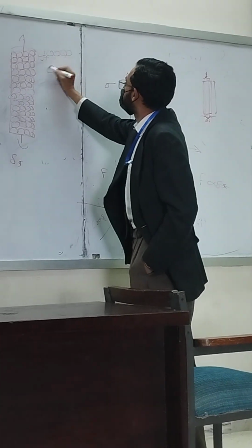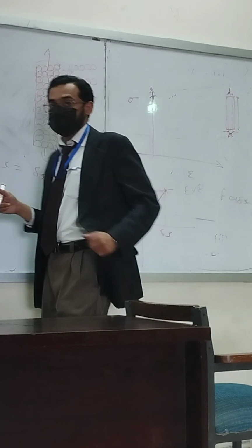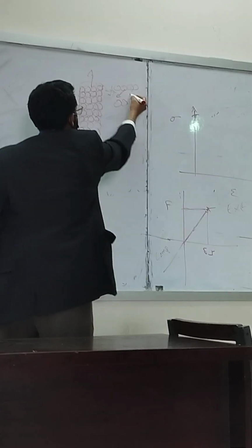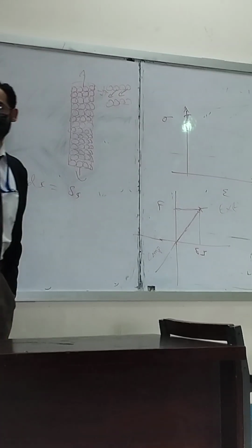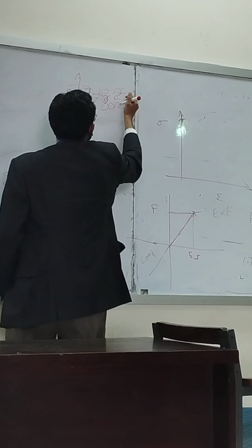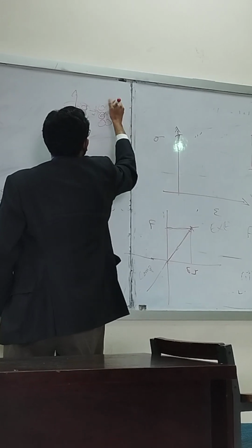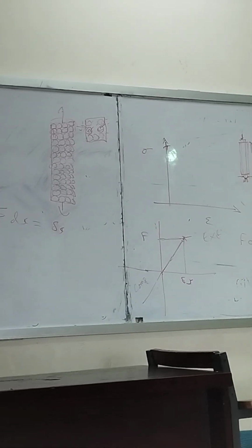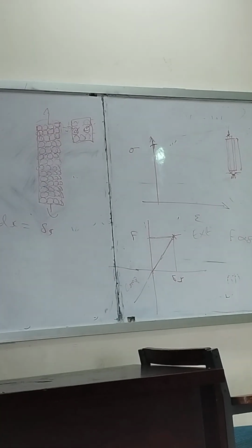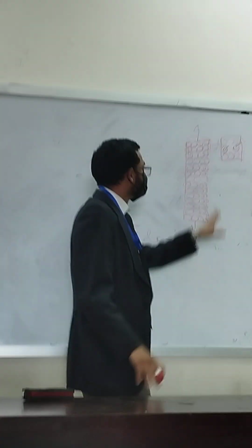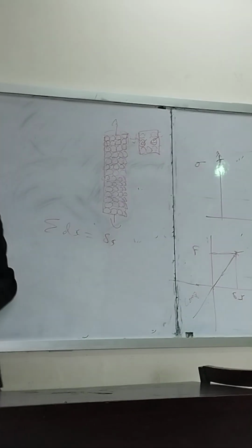Actually, what is going to happen is, with a small force, the interatomic distance is going to increase in size such that it is very easy for this atom to diffuse into this location. It can change places. What is going to happen now? We are going to get something like this. As a result, instead of having this kind of an arrangement, now these atoms have, because the interatomic spacing was increased to a level that this atom would easily migrate into the void over here or diffuse into that void. So that is why plastic deformation has taken place.